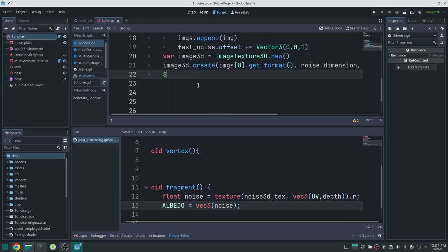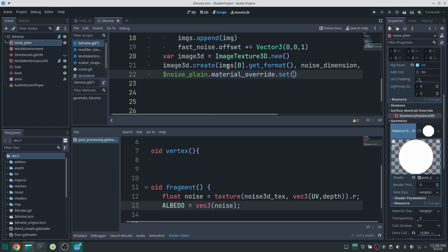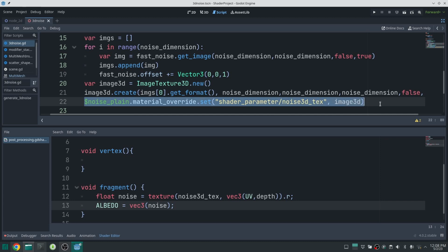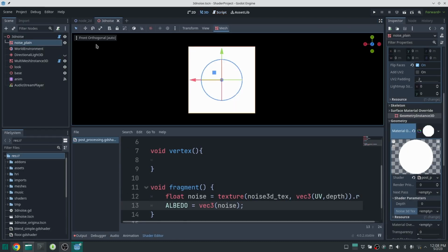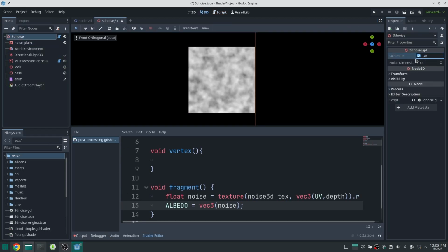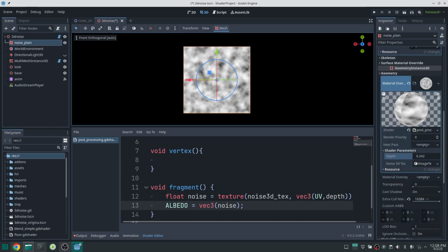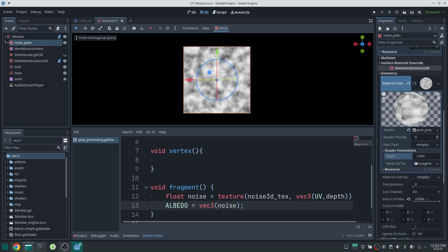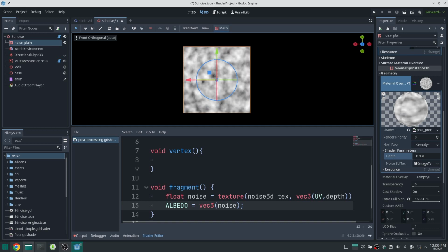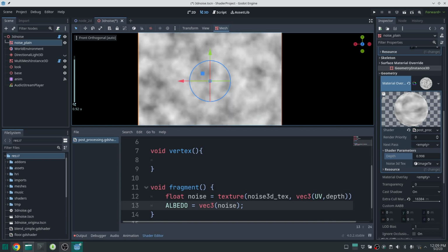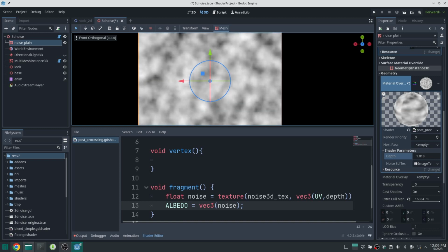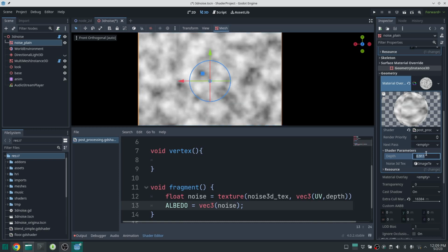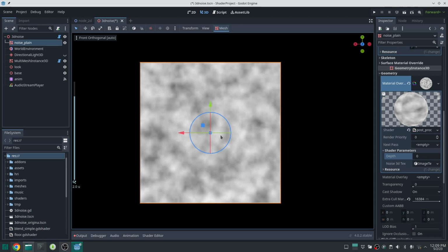Well, here I write a small piece of code which is going to assign this 3D texture which we created to my shader. Now let's generate our 3D texture. And now, if I change my depth variable, I can move inside my 3D space. One important thing is you don't have to stack 64 images on top of each other always. In most cases, with much less texture, that will also work, because when I change the depth value, this will automatically blend between 2 layers.